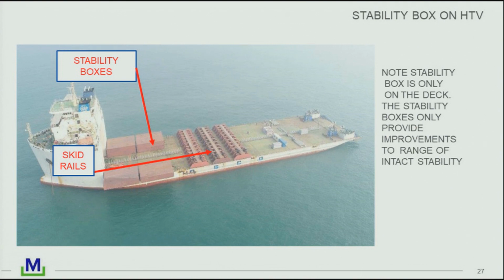Is there any measurement data on these voyages of what are the roll angles that they achieve here? Yes, there are. Because the GMs are so small, 1 or 2 meters, the natural roll period is then perhaps 18 or 20 seconds. That then the roll angles are down to 2 or 3 degrees. Yeah.